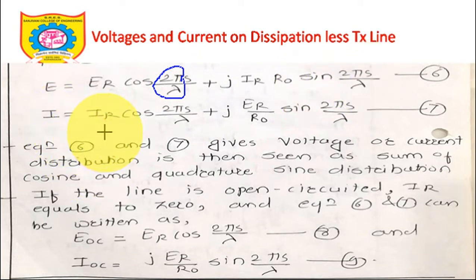Similarly, I can be written as Ir cos 2 pi by lambda into s plus j Er upon R0 sin 2 pi by lambda into s. So equations 6 and 7 give the voltage or current distribution, seen as the sum of the cosine and quadrature sine distribution. Is it okay?